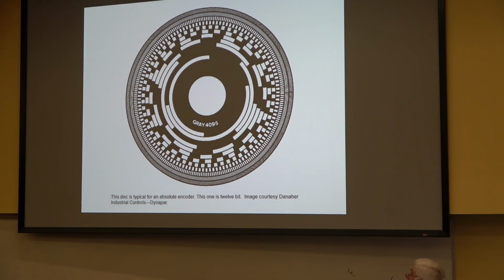And this is what a gray code absolute encoder wheel actually looks like. So it's 12-bit. That means you have up to 2 to the 12th power division of an angle on this thing. And there you go. So if I take any one slice and go 4096 the way around, there's only 1 bit changing as I move along the arc circle.